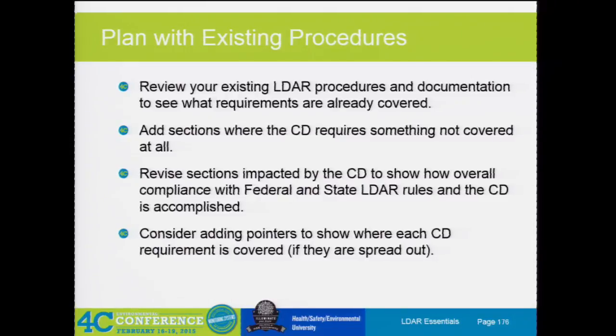So their belief is if you take a proactive approach by finding something that's 100 ppm or a little bit higher but hasn't triggered a leak yet, by torquing it and making an approach to fix it, you're being proactive, so its potential to leak is less. And I don't have the data to prove or disprove that. It just depends. But like we said earlier, if you are going to be doing those, make sure once they torque them that you step back and give it a second to clean out the space around it, because you're going to be pushing everything out and you could get an even higher reading. Usually it's better to wait a little bit and come back.